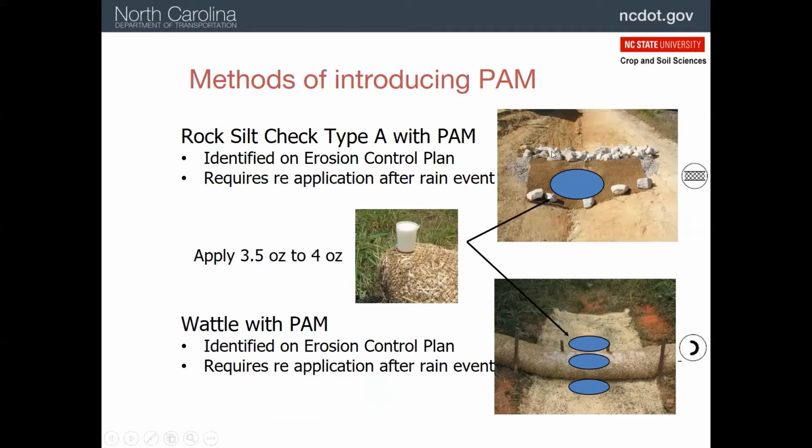Rocks are not a great place to put polyacrylamide. The granules tend to just fall through the rocks and end up in the bottom, and we don't get very good treatment.